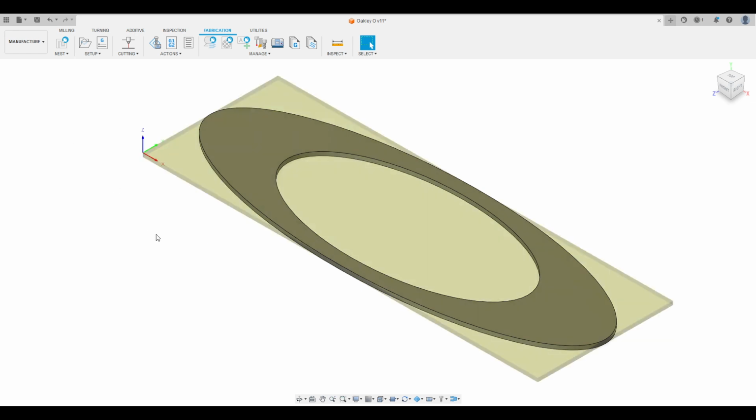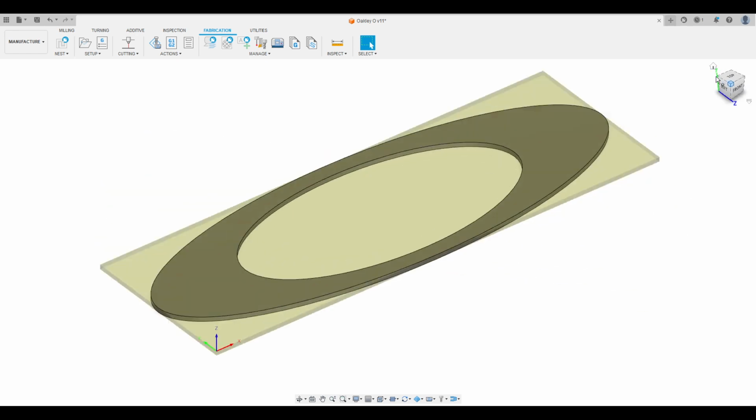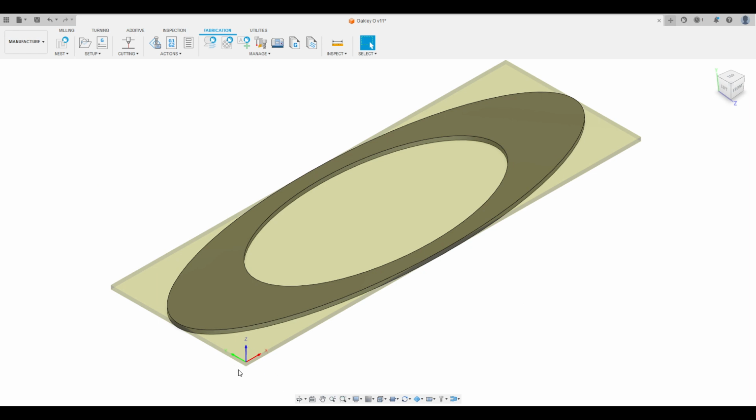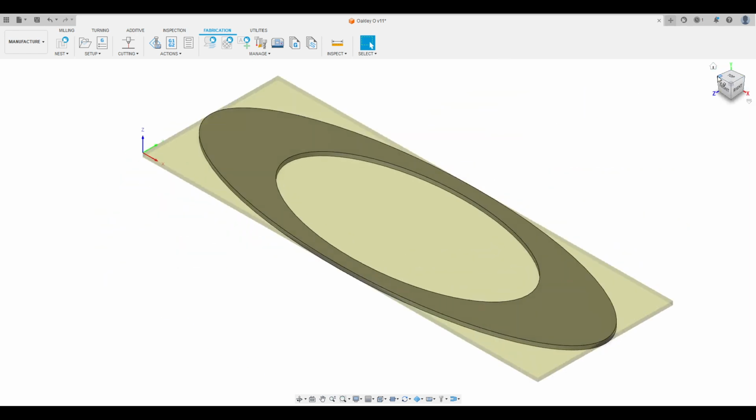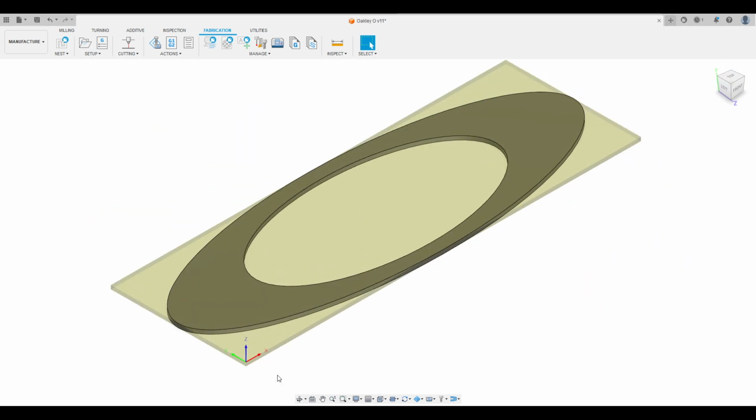Before you move on, verify that your setup looks almost identical to mine. Your viewpoint might be different. You might be going this way, or you might be on the bottom right of your front view or top view here, which is fine. All that matters is that your x-axis runs along the bottom of your stock, your y-axis runs along the side of your stock, and your z-axis is pointing up. If you are struggling with this, stop now and call me over for help.